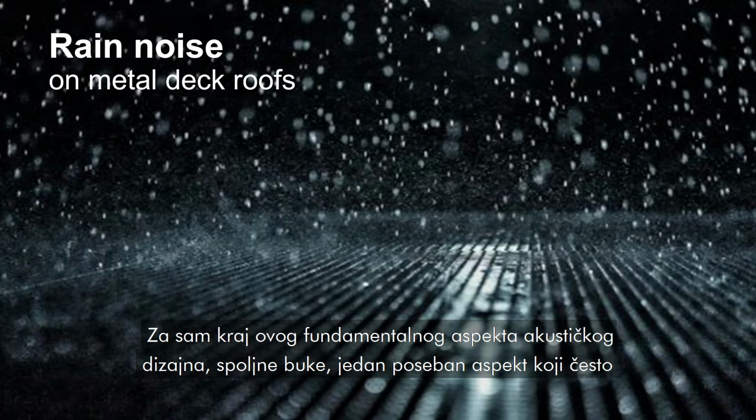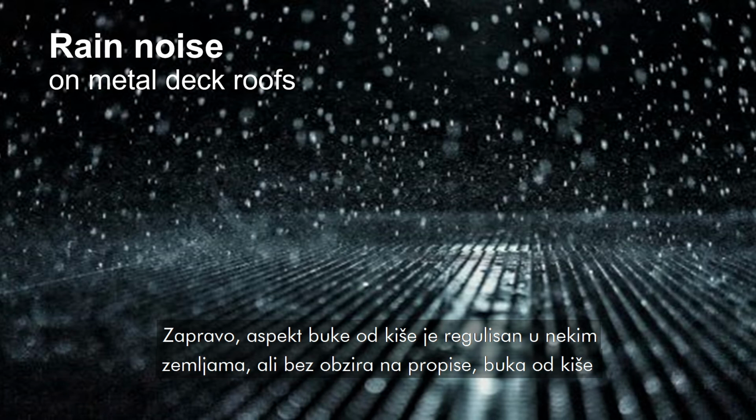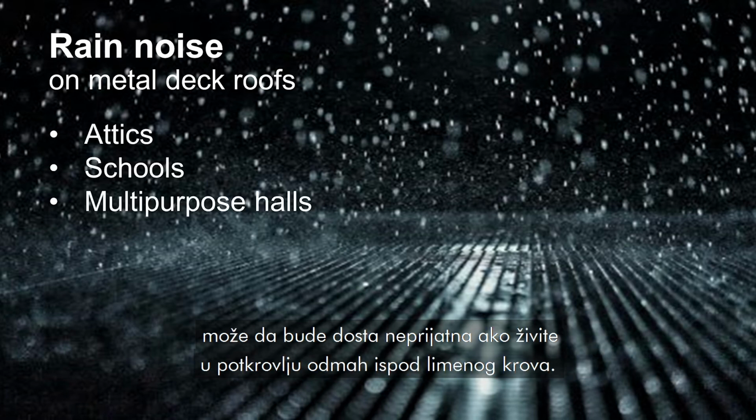For the very end of this fundamental aspect of acoustic design, which is outdoor noise, one particular aspect which does not often cross our minds when we start with the design process: the rain noise. And the rain noise is the most prominent on metal deck roofs. So actually, the aspect of rain noise is even regulated in some countries, but regardless of that, rain noise can be quite annoying if you happen to live in the attic, just below the metal deck roof.